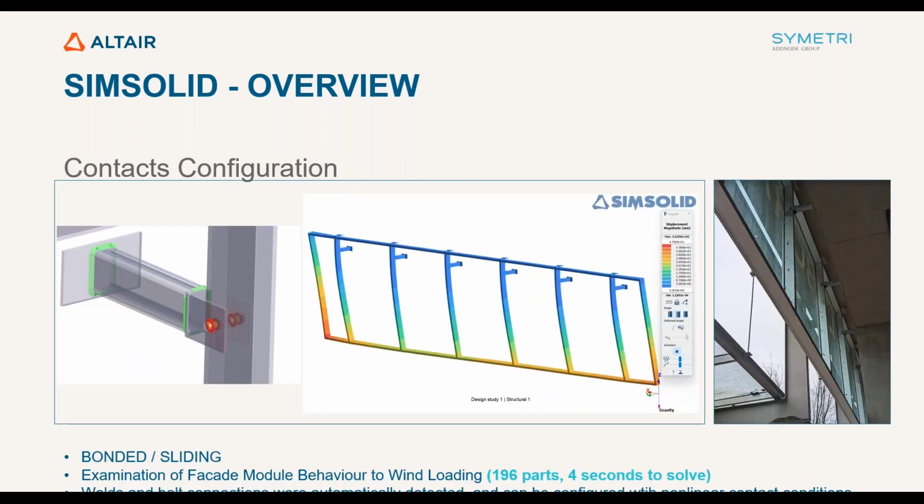we can actually customize contacts. So whether it's a bonded contact like a weld, or whether it's a sliding contact which is held by bolt connections. And the example you see on the screen is 196 parts, and it was literally 4 seconds to solve. And if you have welded connections or bolted connections, you can bring them as they are.